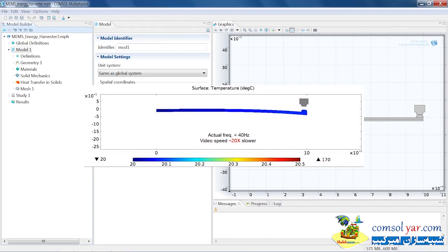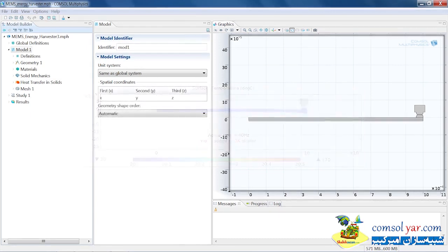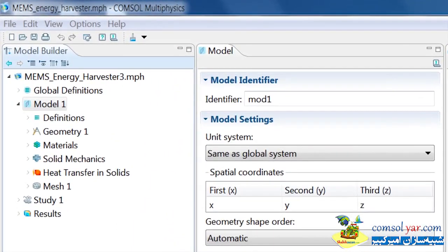This concept model takes advantage of COMSOL Multiphysics' ability to couple together multiple physical phenomena into one simulation. We solve both the solid mechanics equations with thermal expansion and contact, as well as the heat transfer equations. Additionally, the simulation includes pressure-dependent thermal properties in the region local to the contact. Let's take a few moments to look at how this model was set up.